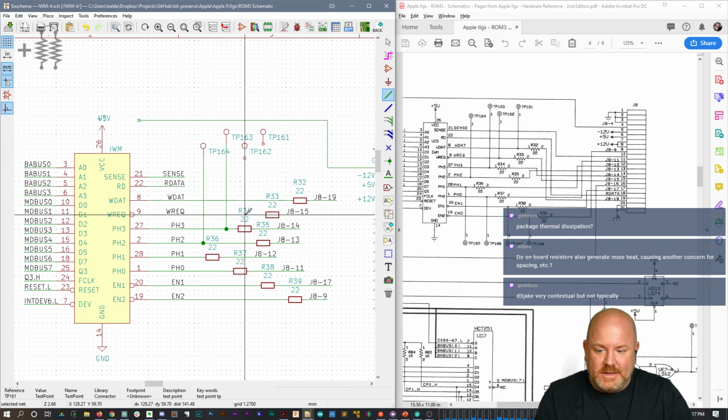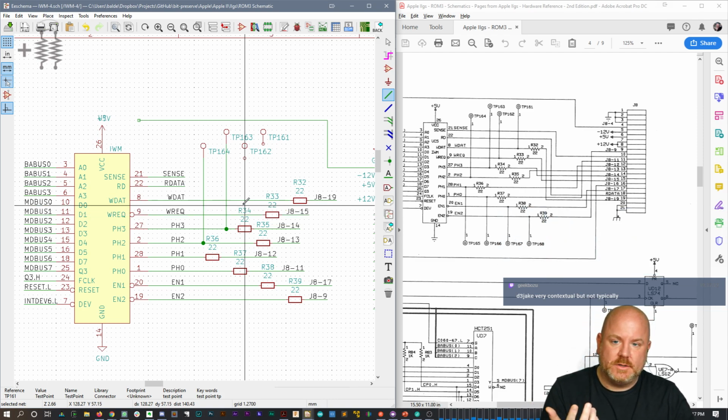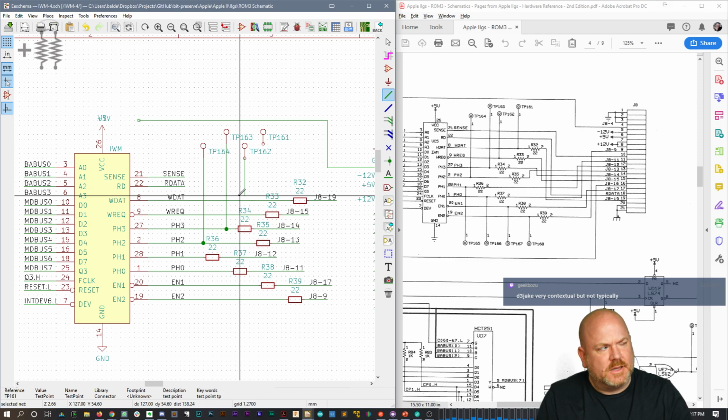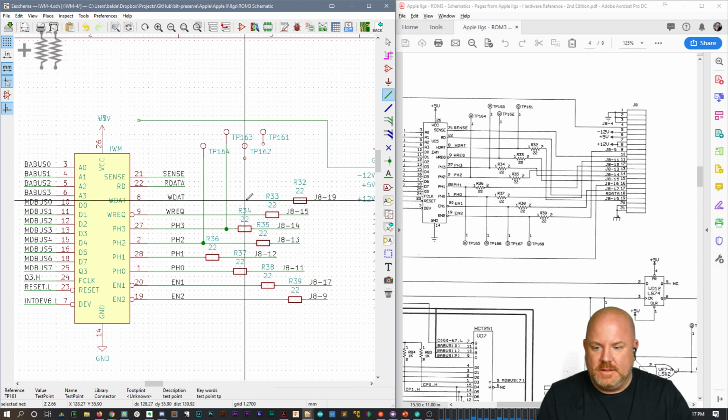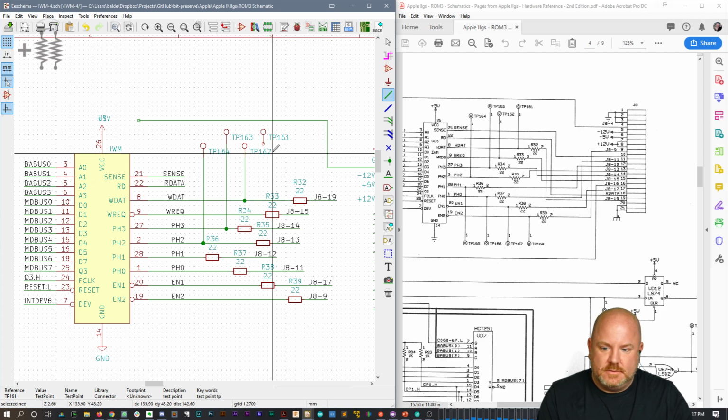But the other way they do it is, if it's a CMOS process, they just use a MOSFET, and it's basically the resistance between the drain and source, I think. Now that I said that out loud, I might have the process wrong. But the point is that a pull-up resistor is actually just a transistor because it's a lot smaller than a resistor. However, it's much harder to control the resistance. But for a pull-up, you don't care what the value is. So that's why they get used. Anyway.